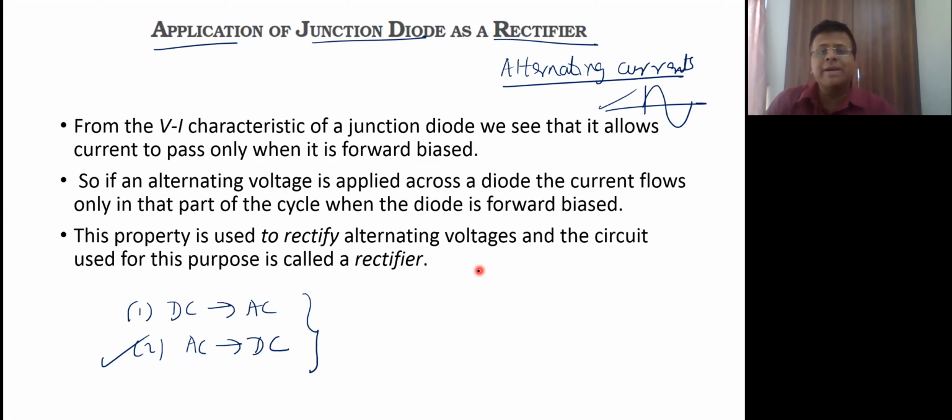See, all your devices, they need DC only. Like right now I'm using this laptop. This laptop doesn't require an AC current. It actually requires a DC current. So even if you have an AC current which is generated and coming across the transmission lines, you need to convert that AC into DC. Otherwise, this device cannot operate at all, isn't it? So that's basically one of the functions of the rectifier.